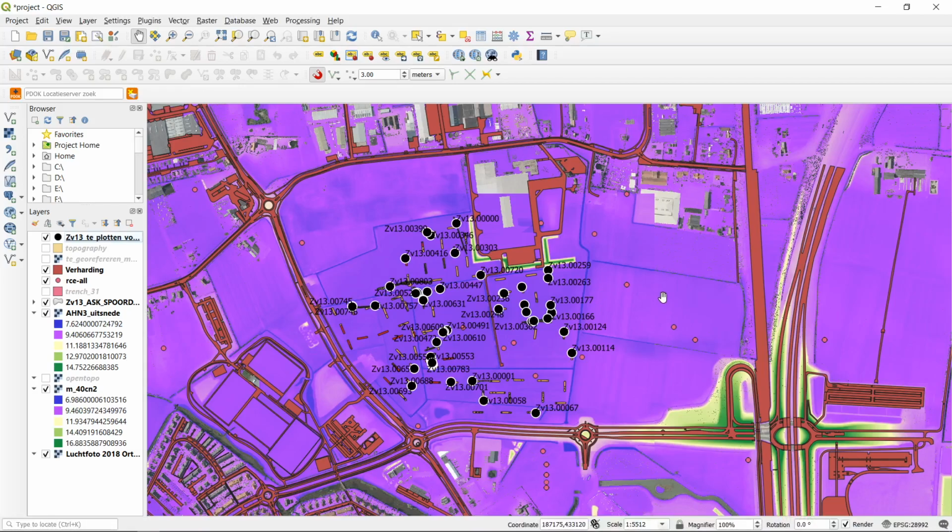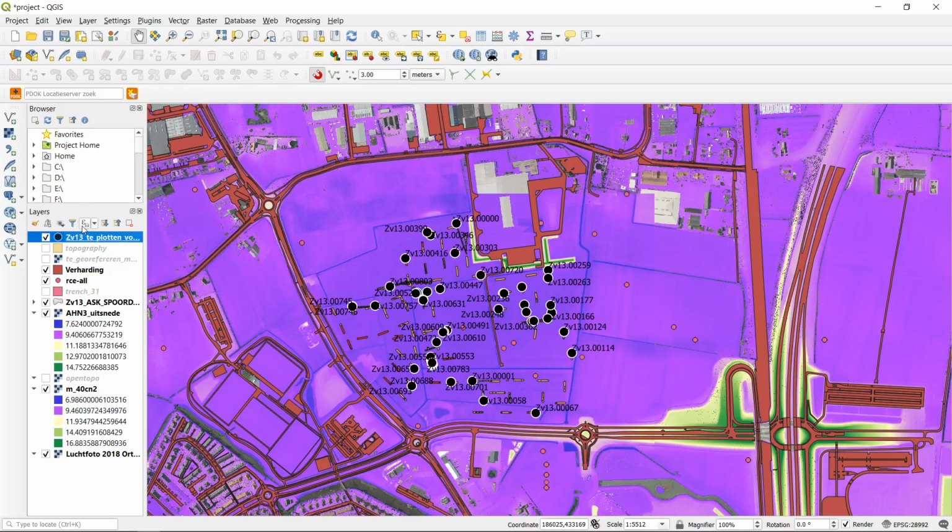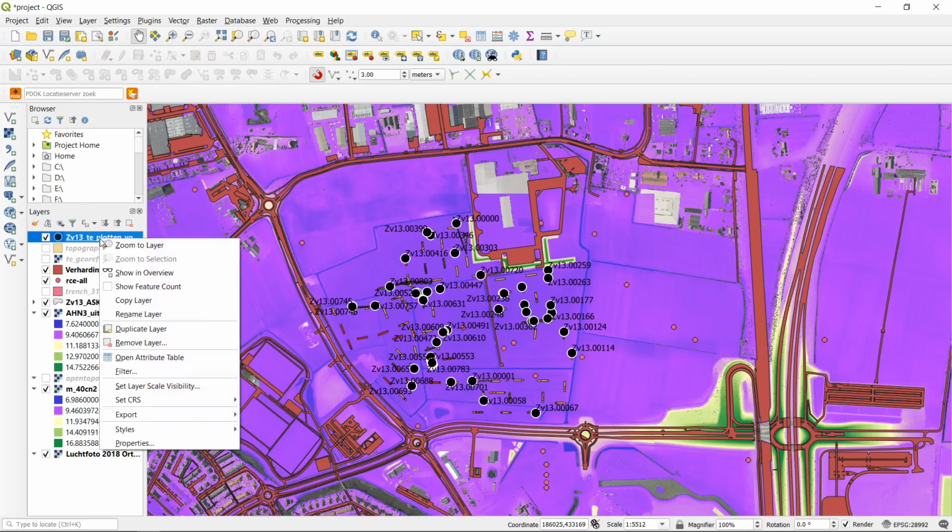Now there's one thing I should add, and that is that this QML layer style definition is not only saving the information on the Symbology tab, but it's also saving other definitions like the label definitions. So if you would, for example, in addition to specific color ramps and other raster visualization, also have styles for the vector data.